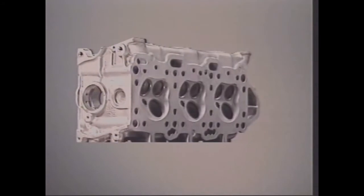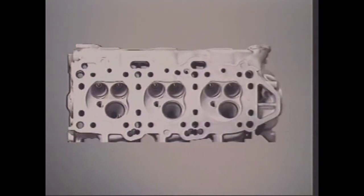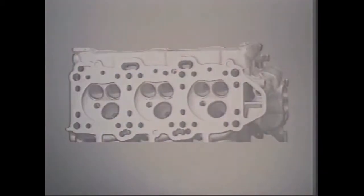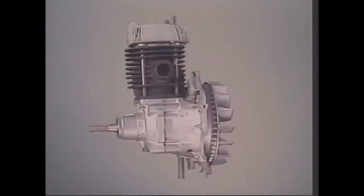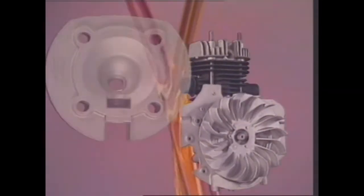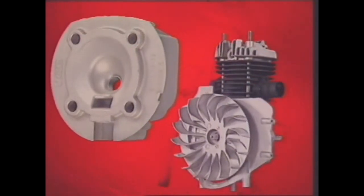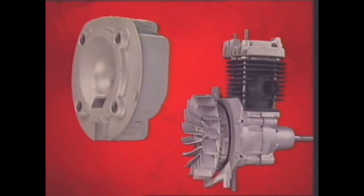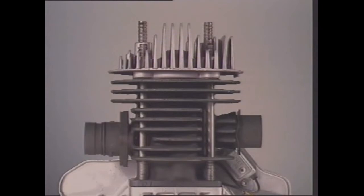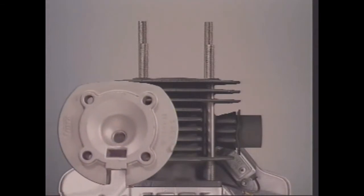The 4-stroke petrol engine has other passages cast into the head to carry oil for lubrication and coolant for cooling. In a 2-stroke petrol engine, lubrication occurs by mixing oil with the petrol, so oil passages are not needed. And if, like many 2-strokes, air cooling is used instead of liquid cooling, there's no need for coolant passages in the cylinder head.